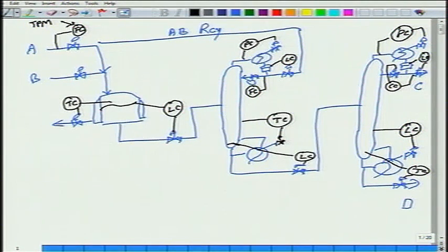Okay, how do I manage the fresh B valve? What will I do? I'll maintain it in ratio with the fresh A. So I multiply by the ratio set point, and that ratio set point gives the set point for the B flow controller, right? And how do I fix the ratio set point? To ensure stoichiometric balancing of the fresh feeds.